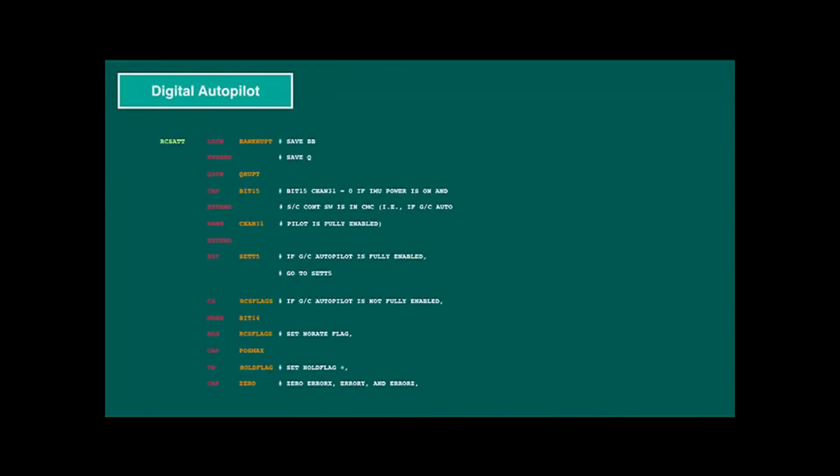Before we leave Earth orbit, let's quickly discuss the digital autopilot. It is the single biggest program in the Apollo guidance computer with about 10% of all the source code, both in the command and service module as well as the lunar module. The implementations for each vehicle are significantly different though, due to different flight modes, thruster sets and symmetry of vehicle.